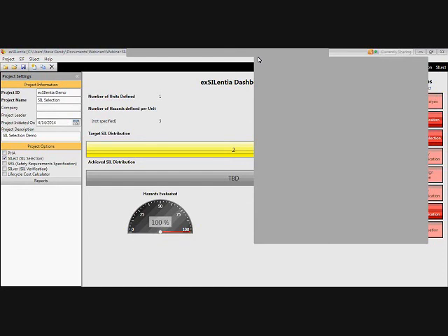You can, as I was saying earlier, if you do end up with a risk reduction factor of 20 from using the frequency-based method, you may say, well, I'm going to specify I want double that, or to be safe, I'll say a risk reduction factor of 60. So I want a SIL 1 still, but I want a risk reduction factor of 60. So that gives you your safety margin.